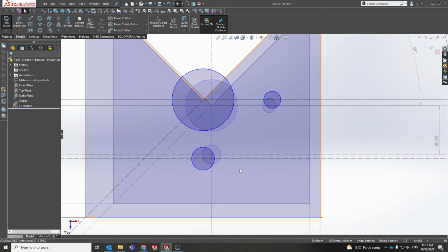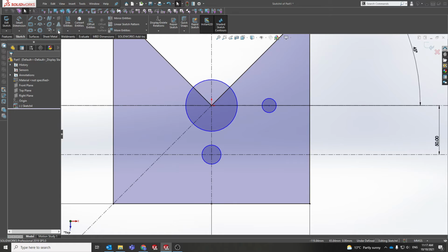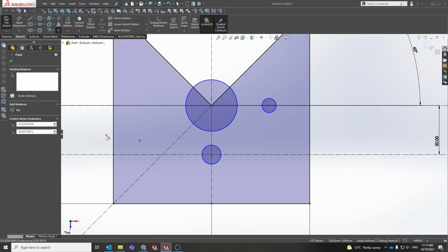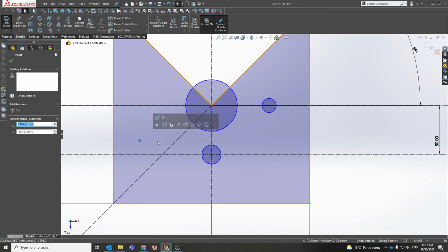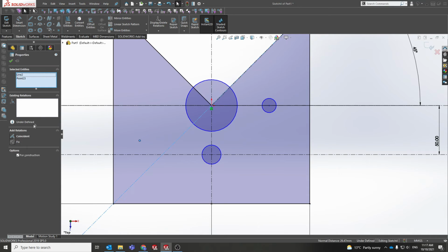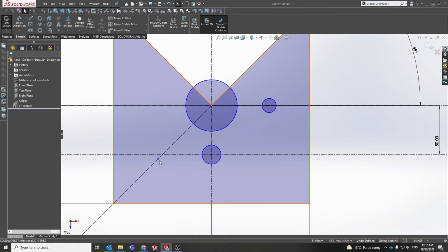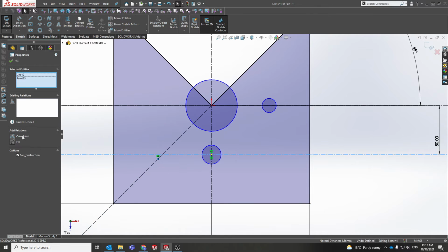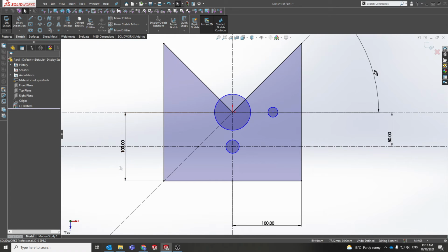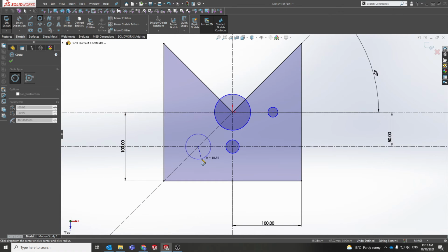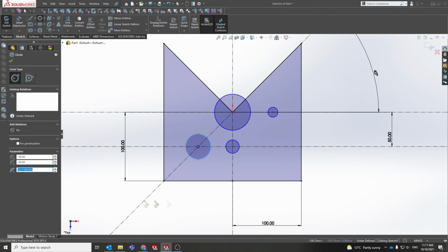The other alternative is to do the exact same, but using a point instead. So I'm going to just drop a point down instead of trying to get this intersection. It just won't automatically snap. So I'm going to go point, holding Control, I'll select this line here, coincident. Do the same again. And that's now locked on there. And then if I want to draw a circle on there, it'll snap to that very nicely.